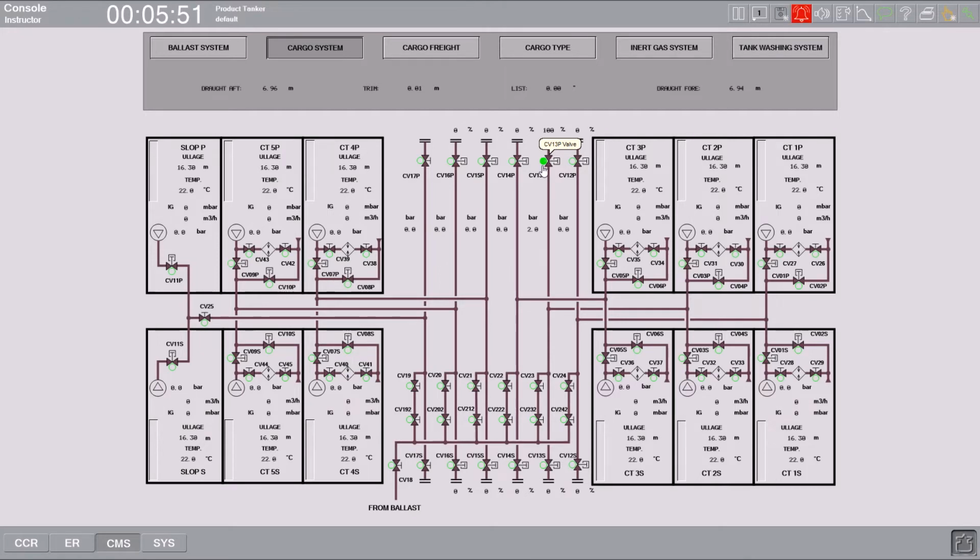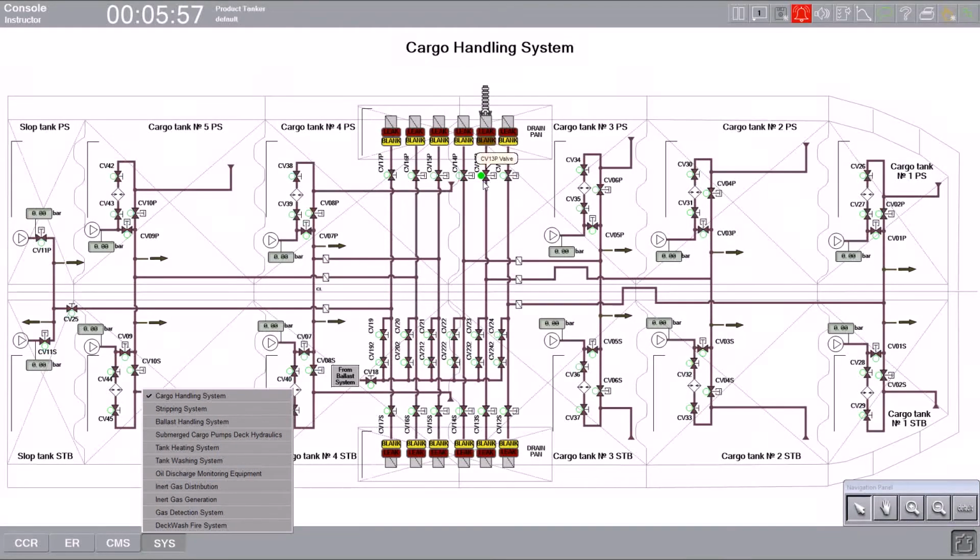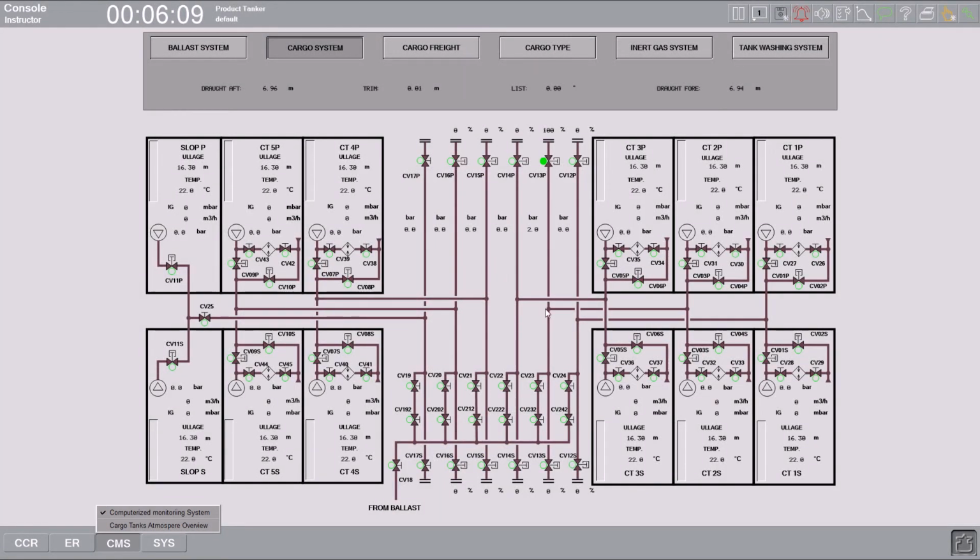Then you can return to the cargo and see this cargo is still not running. Why? Because we have another valve to be opened. This valve is called the drop valve. Check the number also, going back and find it on the line. That's the line which you have to open for the cargo to run into the cargo tank. Open it. You can open it by double click, and these valves can be either open or closed. They cannot be partially open.